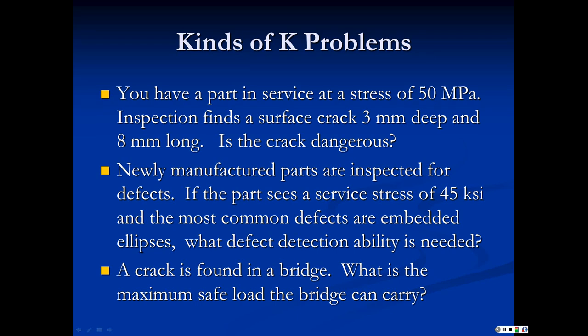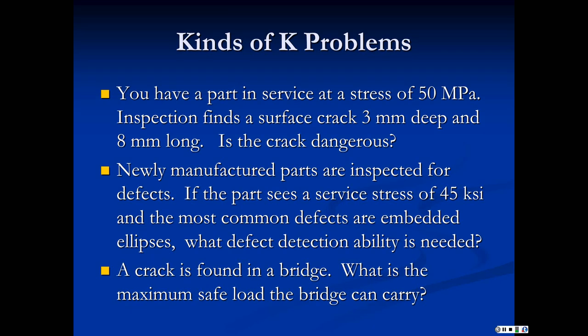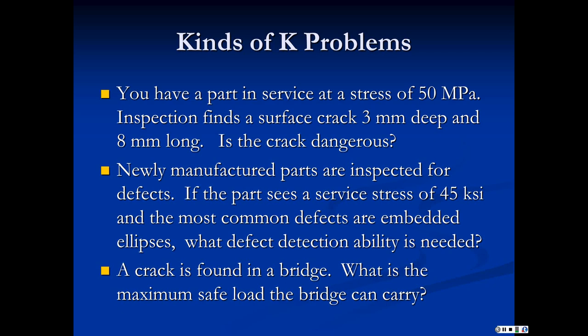Finally, you might run into a situation where you find a crack in a structure, and you measure the crack, and you know the material properties. And so the question is, how big of a truck can we allow on this bridge? Do we need to downrate the loading of the bridge so people don't load it to an unsafe level? And so now you're worried about what is the allowable stress.